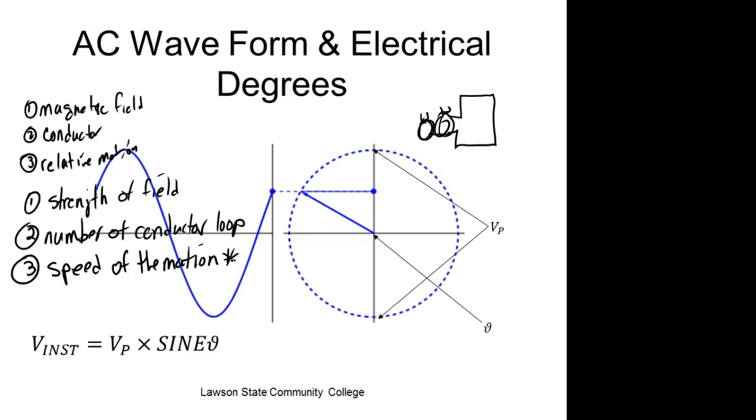But with the regulator, just say I've got a bad alternator but it has a regulator, when I go out there and turn my car on, is it still going to measure 14 whether it's good or bad? No, your battery only puts out 12 volts. Your alternator puts out 14. If you measure 14 volts, your alternator's working. You're not going to get 14 volts from the battery. You get 12 from the battery.